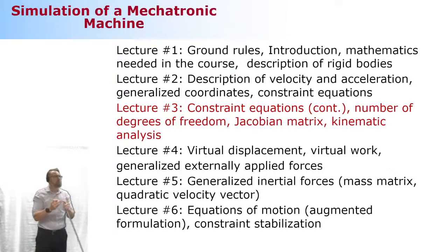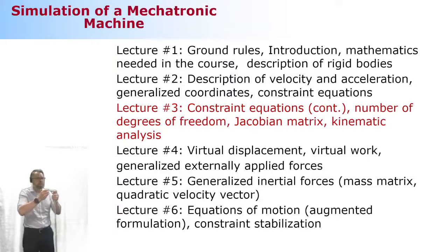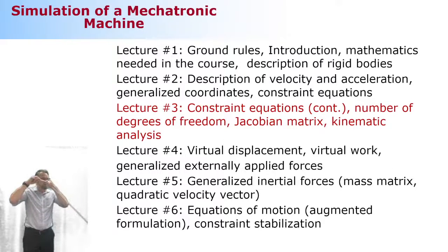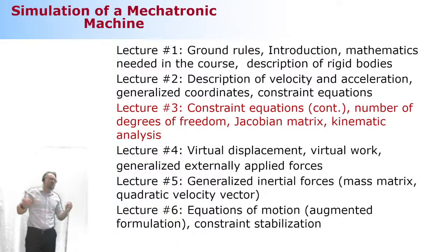Joints have the ultimate force, power, however you want to put it. It means that they cannot separate anymore, regardless of the amount of force. You know that this happens in real life, that if you've got a lot of big force, like this, I can separate the revolute joint. It can happen in real life. When we do the simulation, that's not the case. They cannot separate. They are always something we can obey. So they are not going to be joints that break because of the forces. That's something we are not touching in this class.